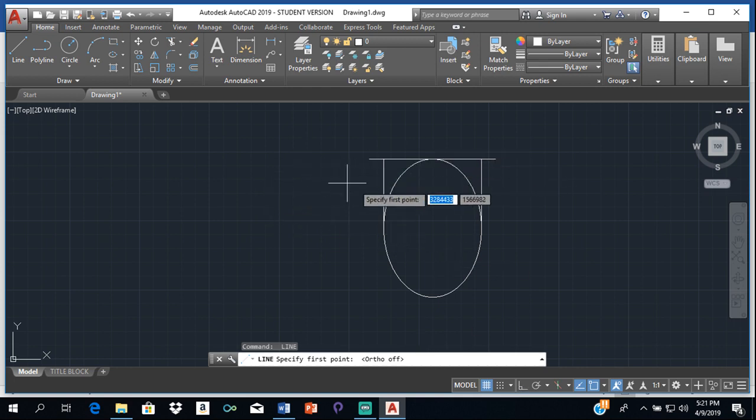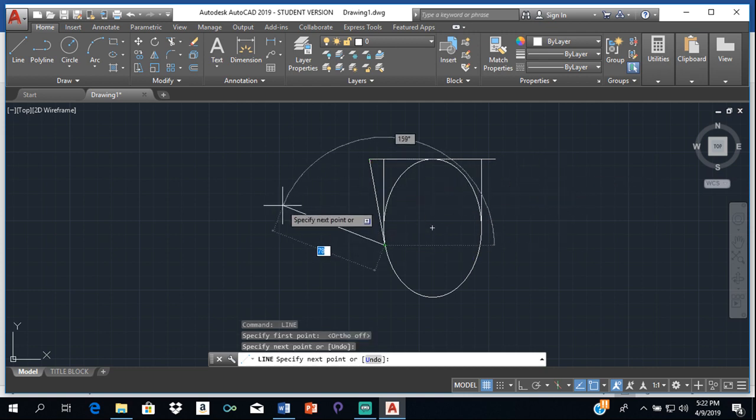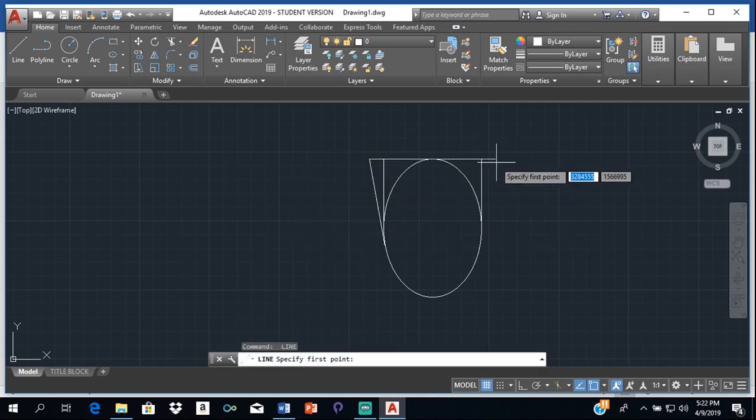we're going to be drawing a diagonal line, and ortho doesn't allow you to draw a diagonal line. So turn off ortho, click on the endpoint right there, and we're going to bring this to this tangent right here. Remember, we're not bringing it to the quadrant or the endpoint right here. We are bringing it to the tangent down here. So once you click here, you just move your mouse down here until you see this circle that says tangent, and you click there.